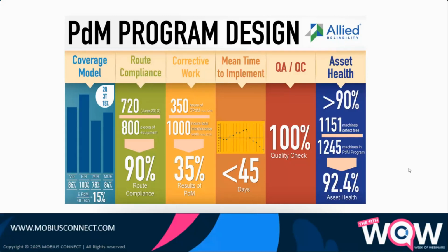You're also looking for those PDM inspections to drive 35% of your labor hours through the results of your PDM inspections. That's identifying failure modes in your equipment that could shut you down. So again, the calculation is we spent 350 hours on corrective work driven from the CM program, and we had 1,000 hours available. 35%.